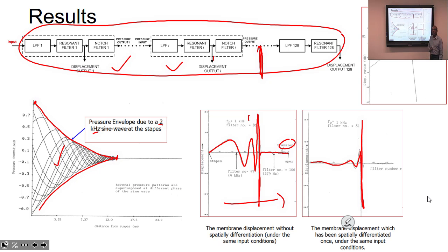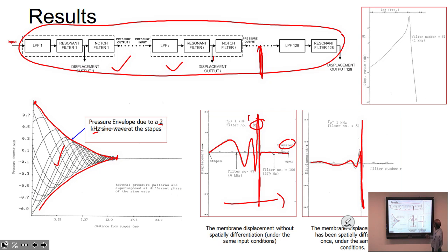It's very sharp. We also ask them for the frequency response of that particular filter. That means if they are looking at the 81st filter, the signal travels through all the previous 80 filters, and they see what it looks like at the 81st filter. That's the frequency response. Because it's traveling through many filters, it gives you a really sharp cutoff, more than 200 dB per decade. It's a pretty sharp filter. Right, and we check all of these when the students have done it.